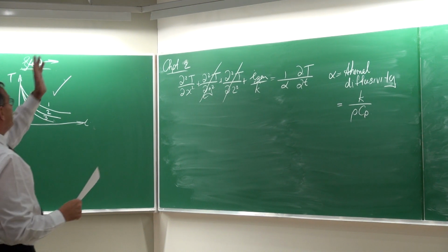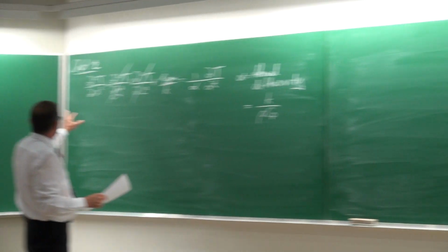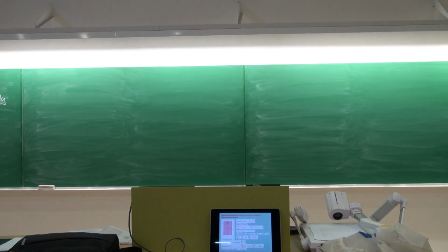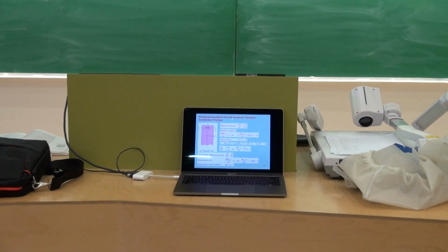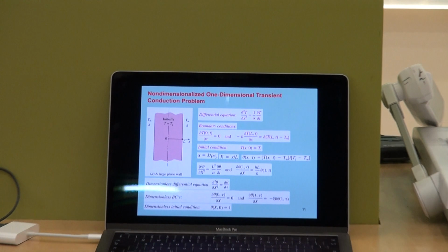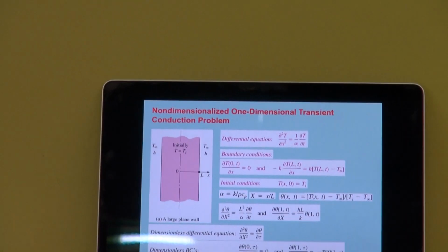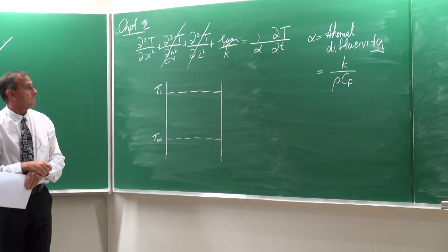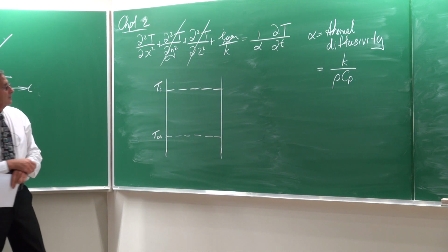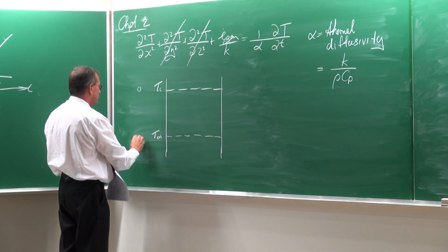So the differential equation, first one there on the slide, you've got it there. And let's just look at typically the boundary conditions. Let's suppose that is the temperature Ti through the plane wall or the cylinder, and then suddenly the temperature is increased to T infinity on the outside. Okay. Let's suppose this temperature is 0 and that temperature is 100.